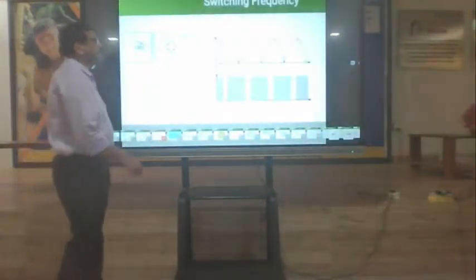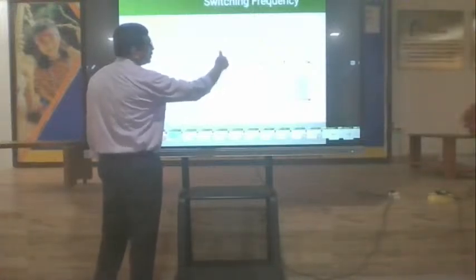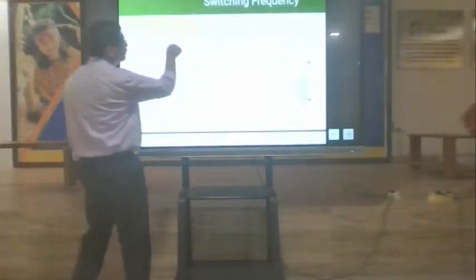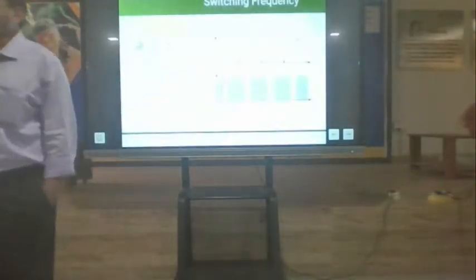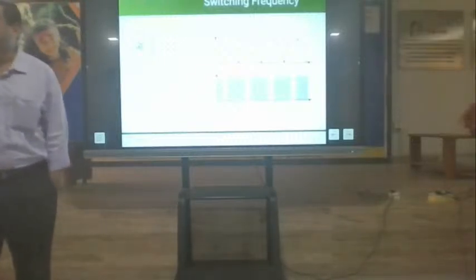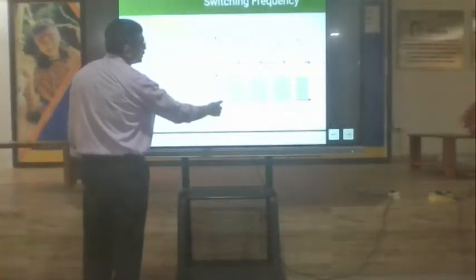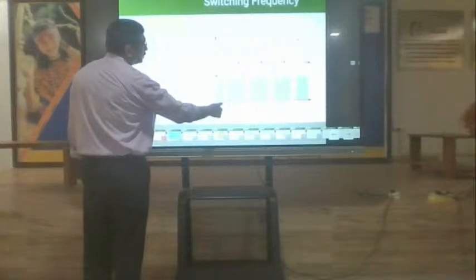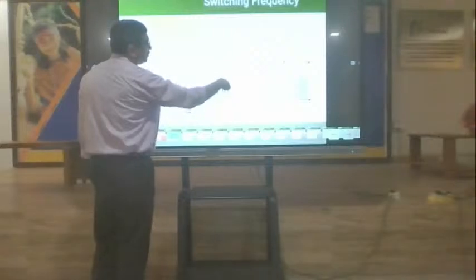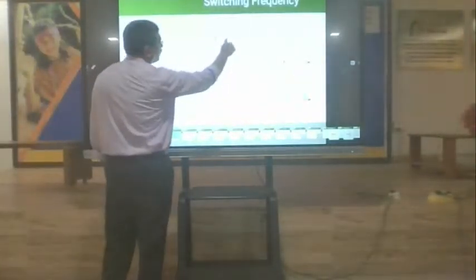Initially when the voltage starts to build up from 0, till certain VF, the diodes have a certain forward voltage. So till the voltage exceeds the forward voltage of the two diodes in the bridge, it doesn't conduct. So till 1.2 volts, it doesn't conduct. From there on, it will start charging the capacitor. As the voltage builds up, the capacitor current builds up. Once it reaches the peak, its voltage is falling.